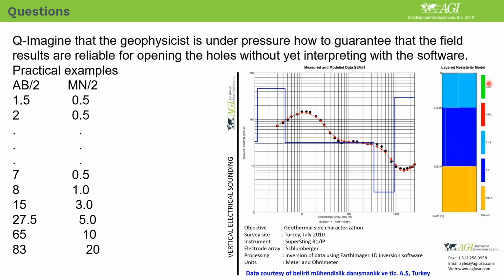But you can see that here the first layer is about 33 ohm meters on this model. Maybe I can estimate it asymptotically, because if you know the shape and behavior of the curve, you can say that. So I will estimate more or less, but this is not apparent resistivity, it is your estimation. That means now you are going to the true resistivity solution.